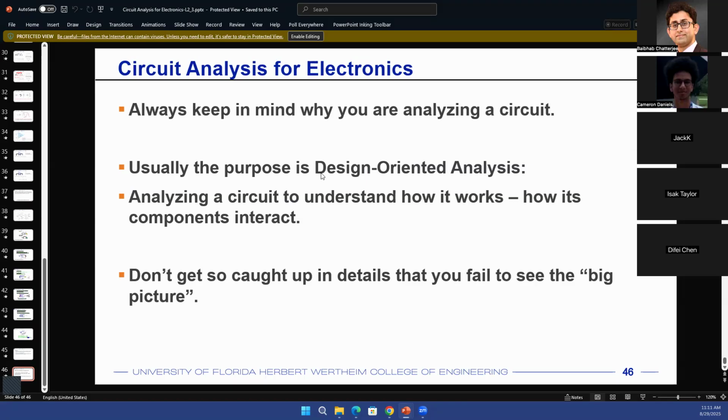Do I want to amplify an AC? Do I want to create a different DC voltage out of it? Do I want to convert AC to DC? Or do I want to just convert AC to AC, but at different power levels or different voltage levels? Depending on that, your circuit topologies will change, your circuit architectures will change, and the elements that you'll be using in the circuit will change. So everything depends on eventually what is the application that you are trying to look for.